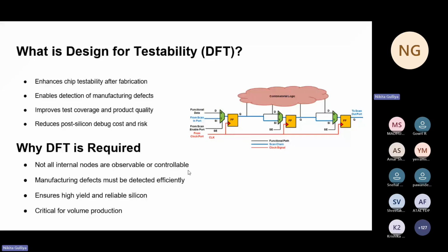There can be issues later at the stage, such as the chip can be heated up, or there can be sand particles which can go on and cause issues later. So it's better that we do some kind of DFT techniques earlier itself. Common DFT techniques include scan insertion with the flip-flops, where a scan port and scan chain are inserted, and LBIST and MBIST, which are built-in self-test.